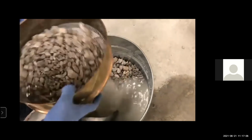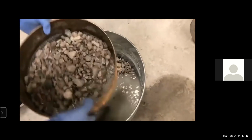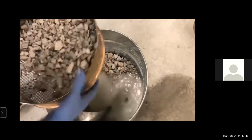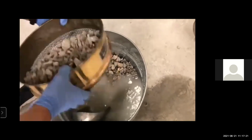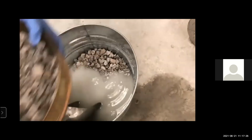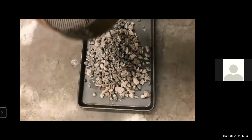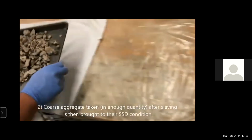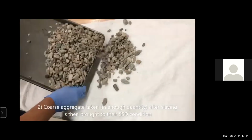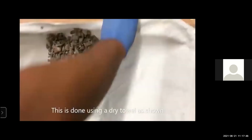We sieve these clean aggregates and remove some absorbed water which is present on this sample. We clean all the dust which is present on our aggregate. We pour these clean aggregates on a sample. Then coarse aggregate taken in enough quantity after sieving is brought to its SSD condition. This is done using a dry towel as shown.